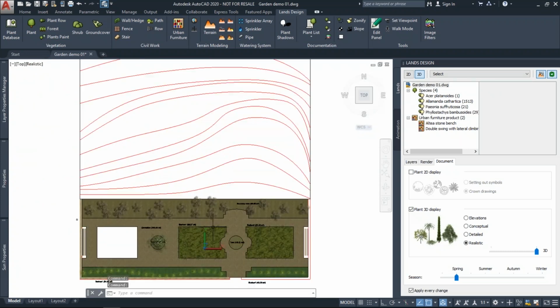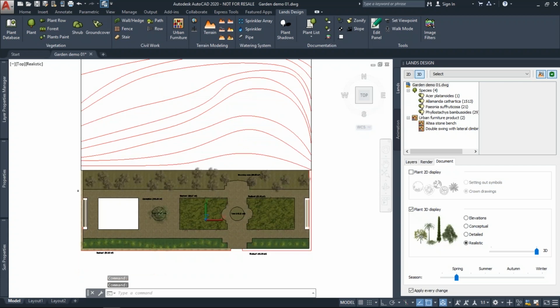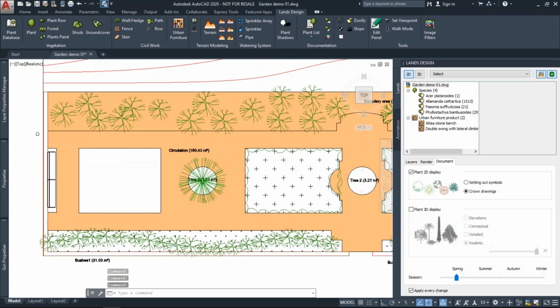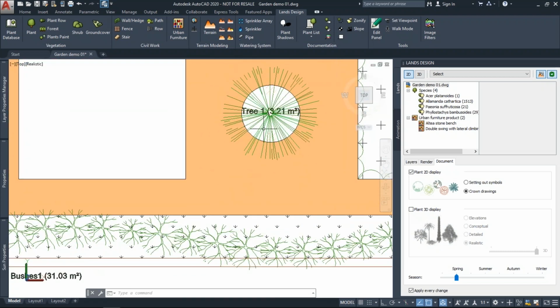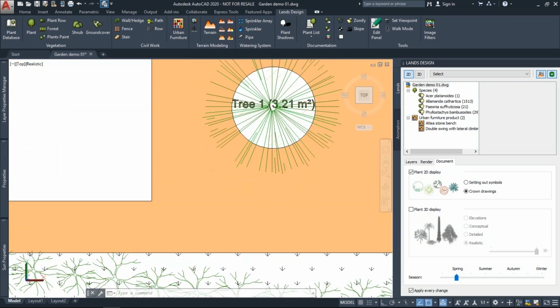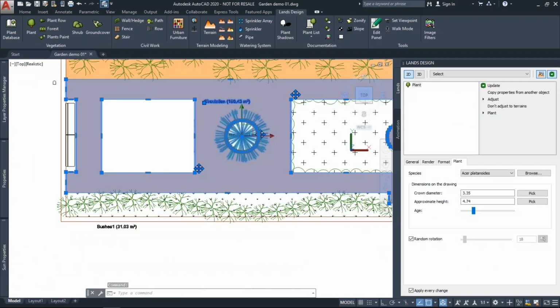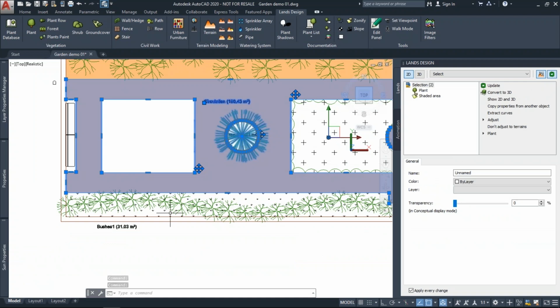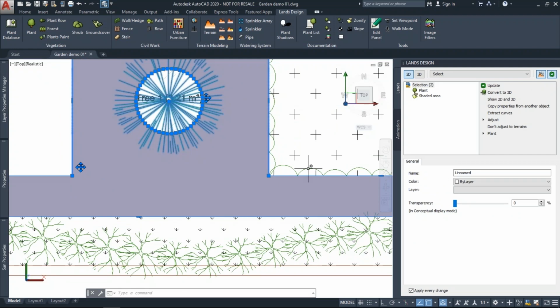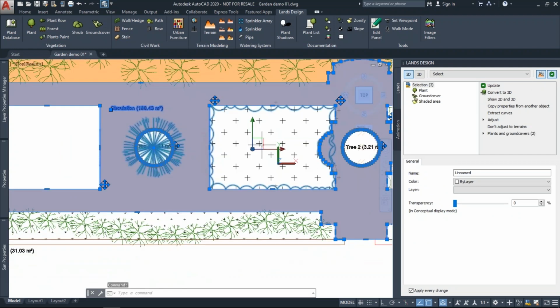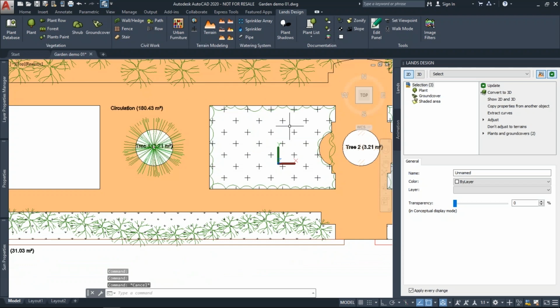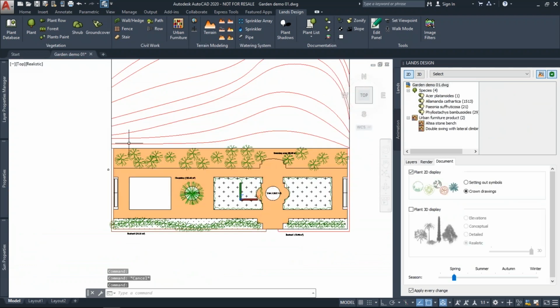And when I select this 2D representation, all the landscape elements will show using a different representation mode. So basically, the trees show the 2D crown. The zones show a hatch pattern instead of texture. And some other elements like ground covers also show a hatch pattern with this wavy contour. And later on, when we generate terrains, we will be able to see the contour lines.